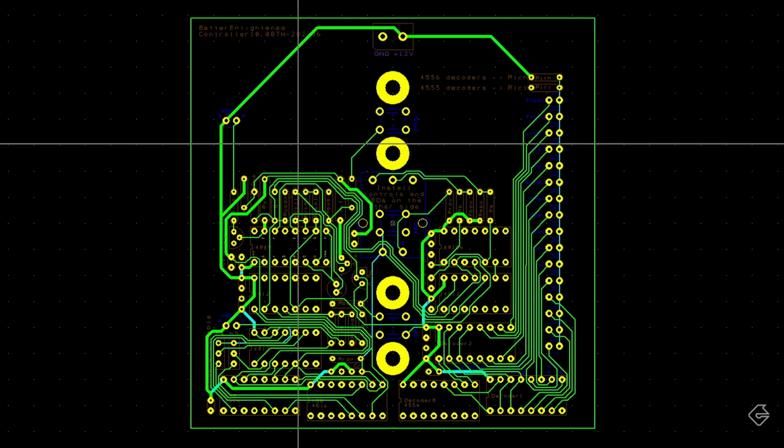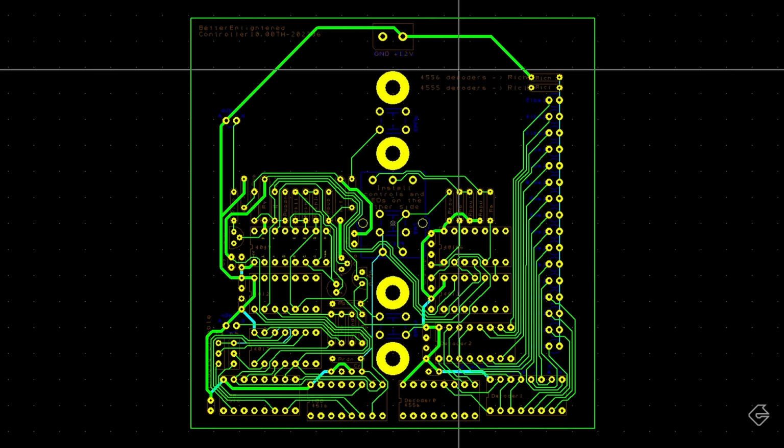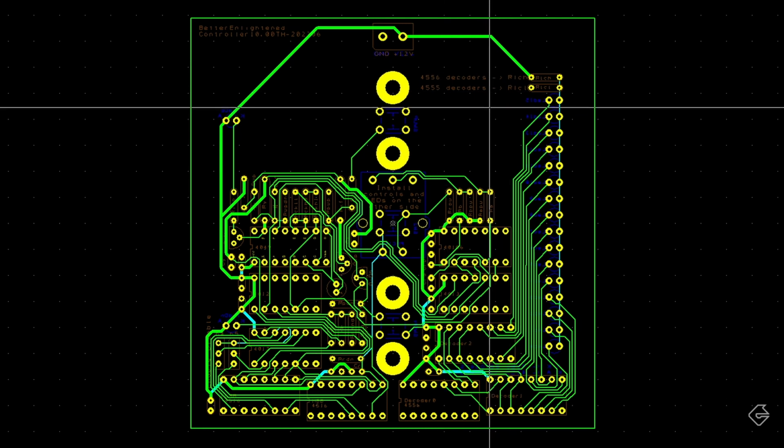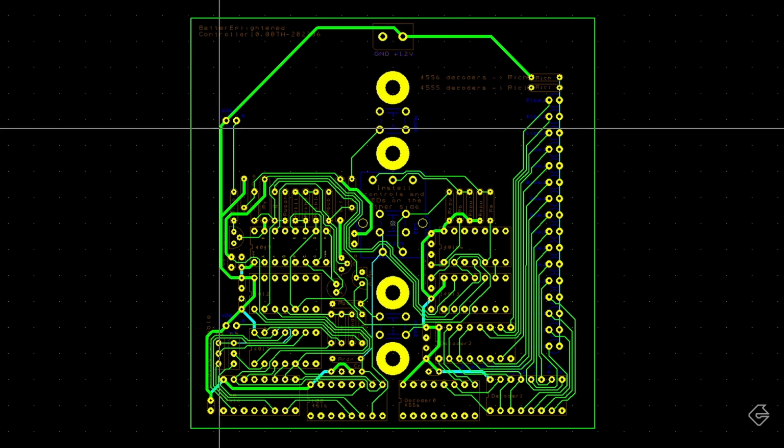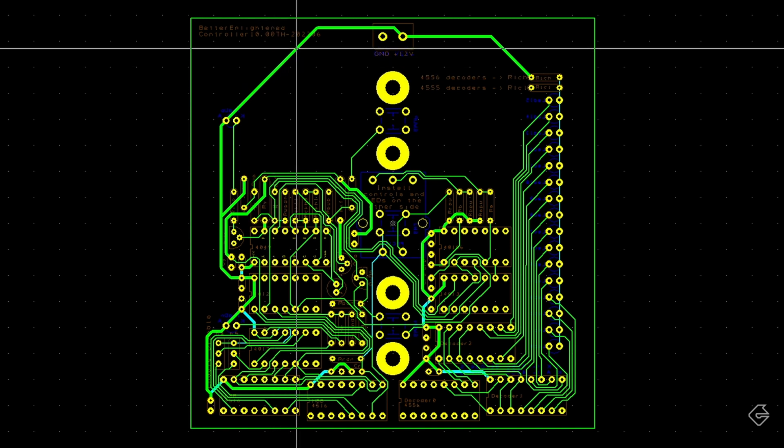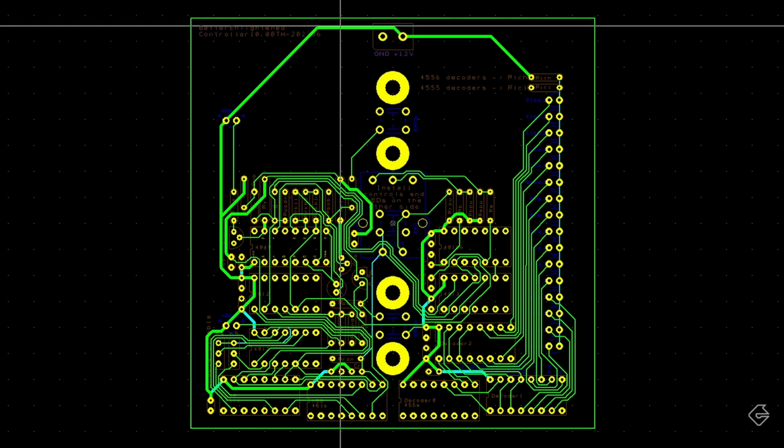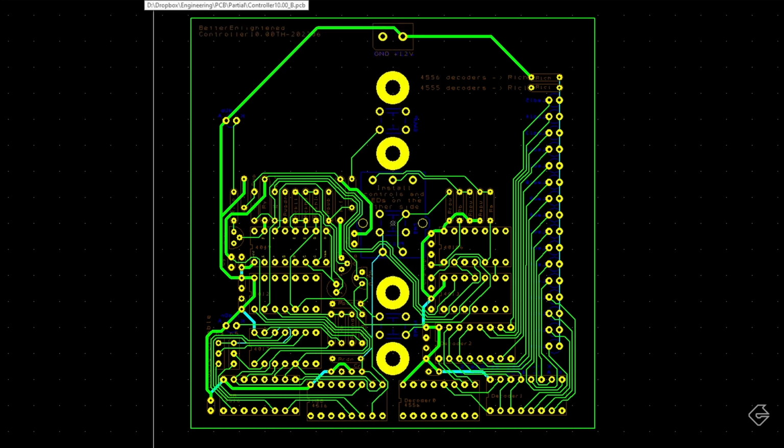And you'll notice there's still quite a bit of space. Deliberate. There's enough space on this board to add two of our LED drivers. One will fit nicely into this space, another will fit nicely into this space. The first thing I'm going to do is make some room. So this is the power line that's coming in from the plus 12 volt in. I'm just going to remove that and get it out of the way for now.